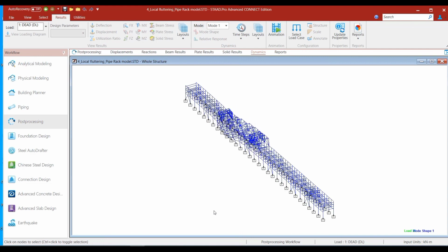This might be a case of inappropriate stiffness, which might be the result of weak members in that region or weak connections of this portion to the rest of the structure. But this may be intended by the structural engineer as well. So we do not really know, and only he can say whether this behavior is an expected one.